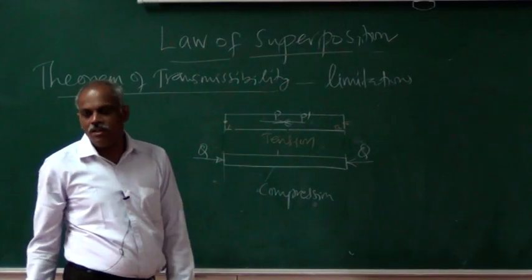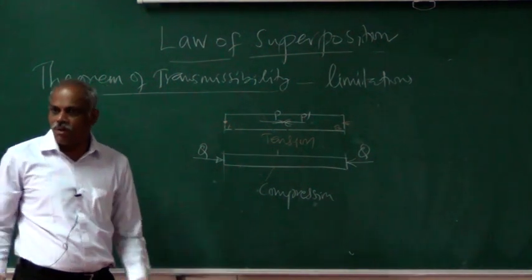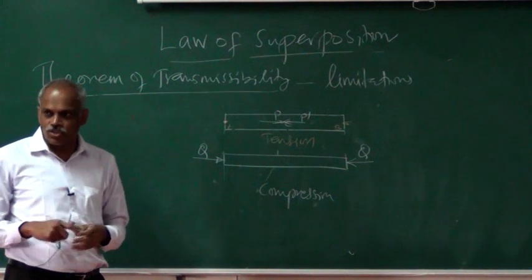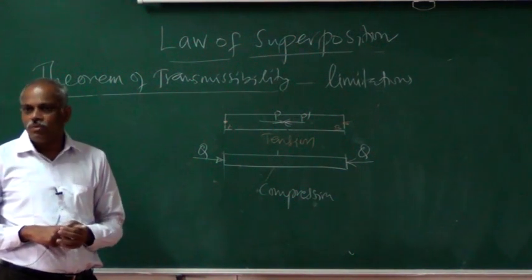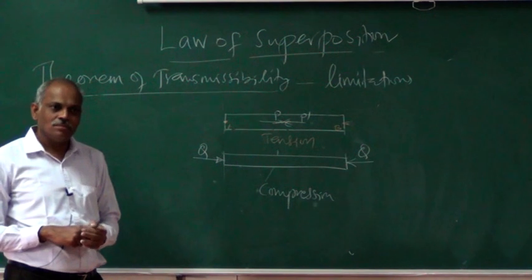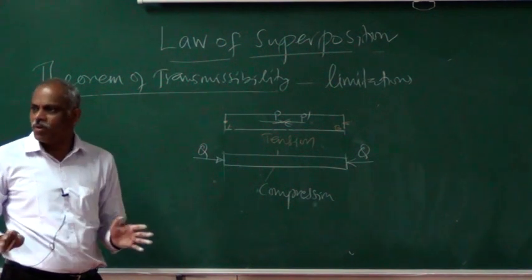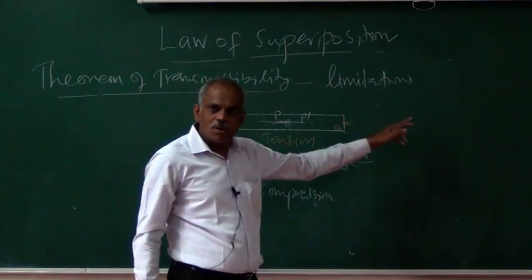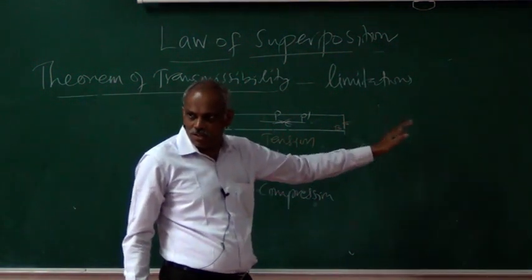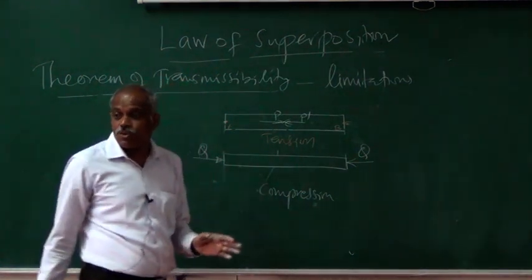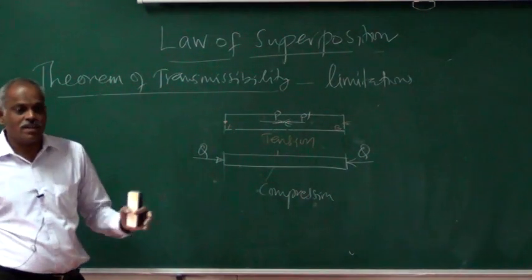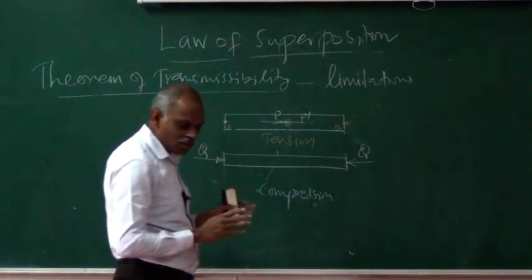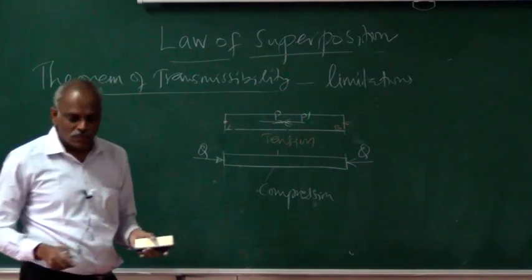What are the limitations? When you are concerned about the internal stress situation also, you cannot use this arbitrarily. For statics it is no problem. When it comes to problems in strength of materials or problems involving this, you have to be cautious. You don't say that I use the theorem of transmissibility, I just transmit it. So that is one limitation that you have to take care of. Do you have any doubt?